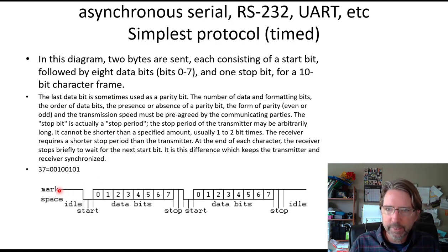And the way it works is when we're not sending anything, we leave the line at the high voltage, 5 volts on your Arduino, and then you're listening, and when you see that wire, the transmit on your Arduino, TX, drop to 0 volts, we know that there's a transmission coming. So the start bit changes the state here, and you start your stopwatch on this falling edge, because you know